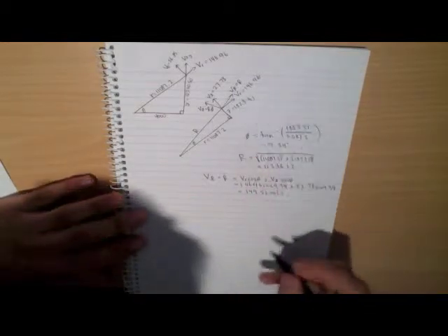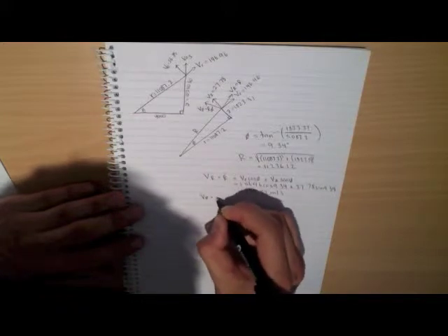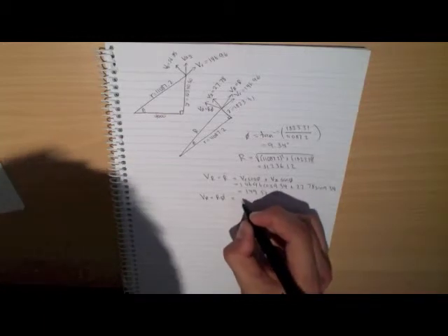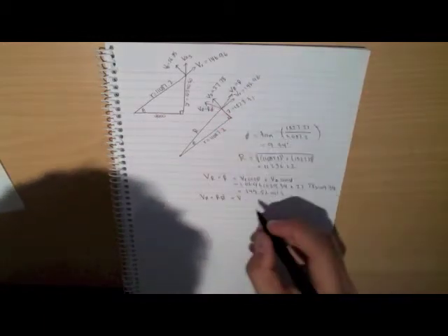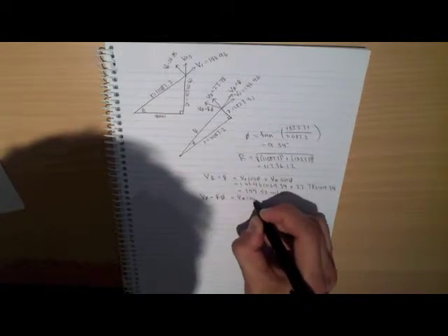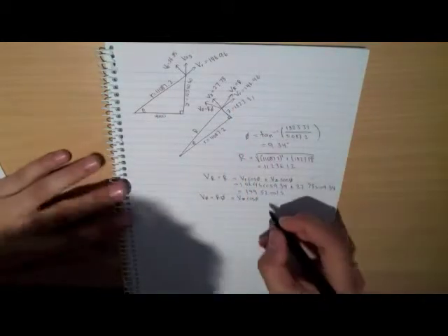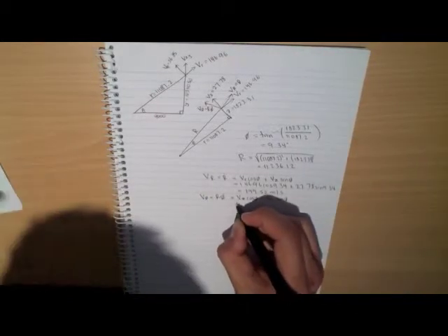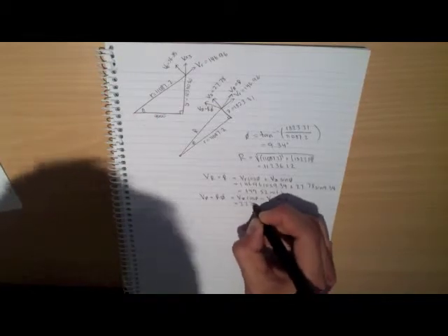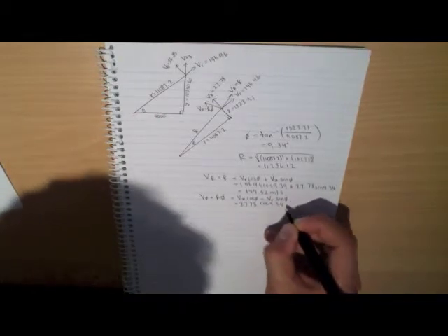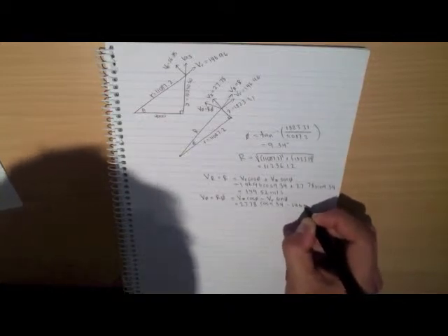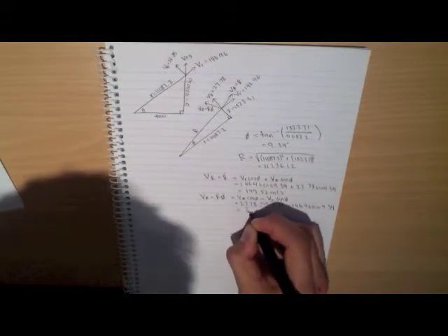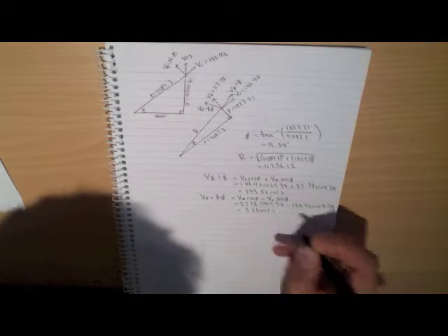Then we can work out V phi similarly. We have V phi is equal to R phi dot, which is going to be equal to, we have positive z, so Vz cos phi, and then we've got Vr in the negative direction, so minus Vr sin phi, which is just going to be equal to 27.78 cos 9.34 minus 146.96 sine 9.34, which is going to be equal to 3.56 meters per second.